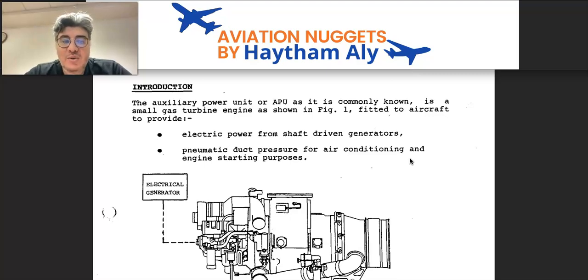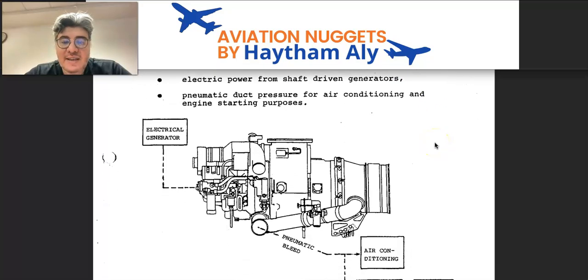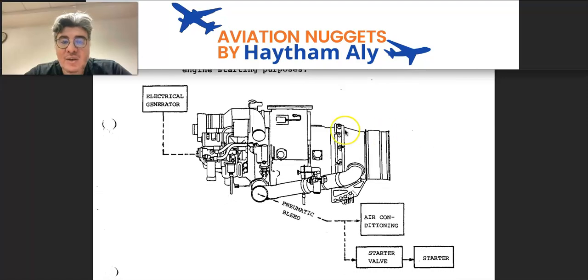Today, everybody, we are going to speak about basic knowledge regarding the APU, the Auxiliary Power Unit. As you can see here, the APU is an auxiliary gas turbine engine located at the aft section of the aeroplane, probably in the tail unit, an unpressurized area, or a fireproof compartment, to allow the aircraft to be independent from the bleed source and electrical sources on ground.